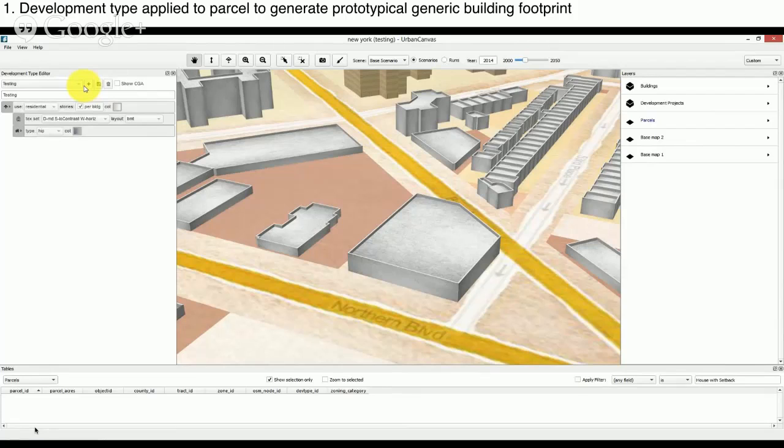That makes it a little conceptually clearer to say that building development types always start with extrusions and turn something into a building, and parcel development types don't really make sense applied to a building footprint, because you're not going to apply zoning setbacks to an L-shaped footprint, because it doesn't make any conceptual sense in the real world. So, complicated answer to a very good question.